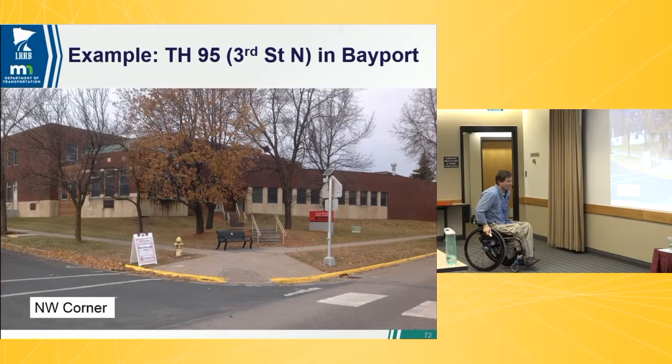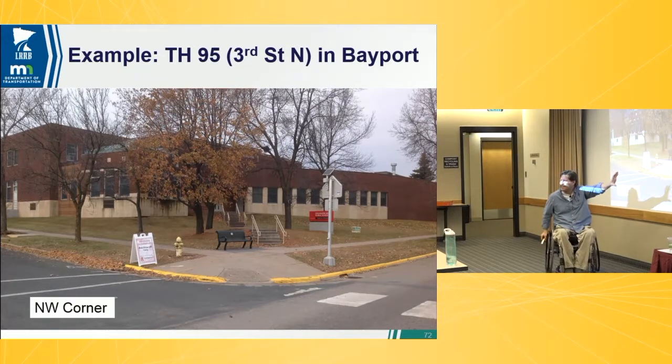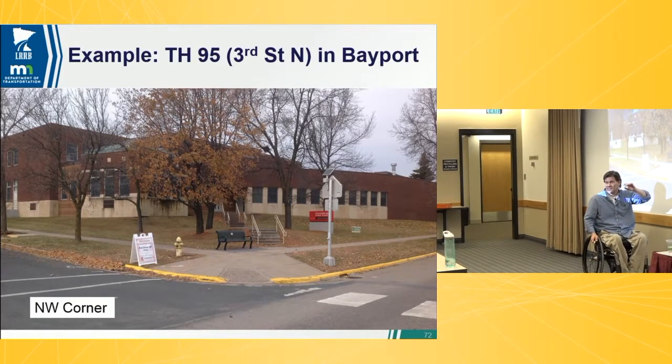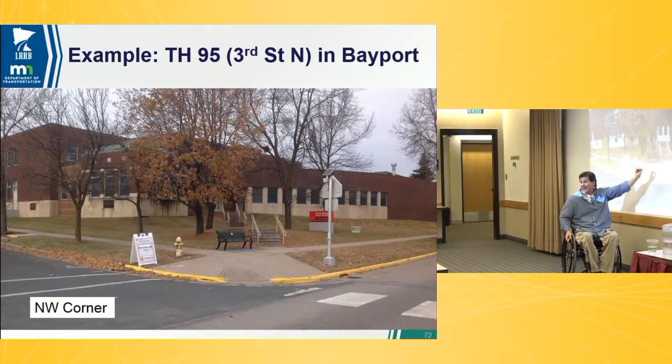Here's all those flights of stairs. Again, 14% ramp. I've got to make up 18 to 20 inches here in one corner. From that flow line to that bottom step, to make it meet standards, make it compliant, 20 inches, let's say, for conversation. It's a lot. So I got to start doing some drastic things here. First of all, I normally don't add steps because you don't want to change the accessibility. You've already got 3 flights of steps here. So I'm going to add 2 steps.